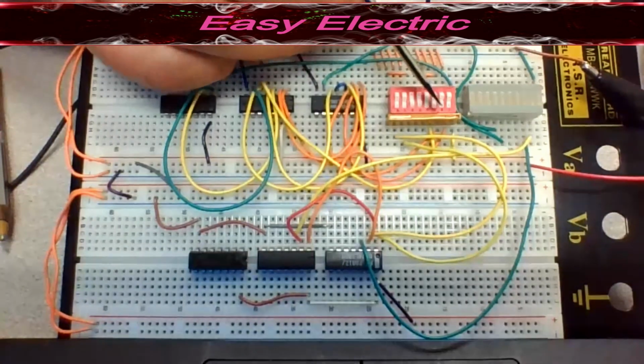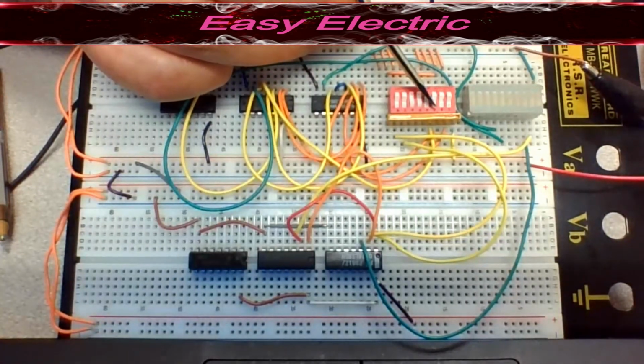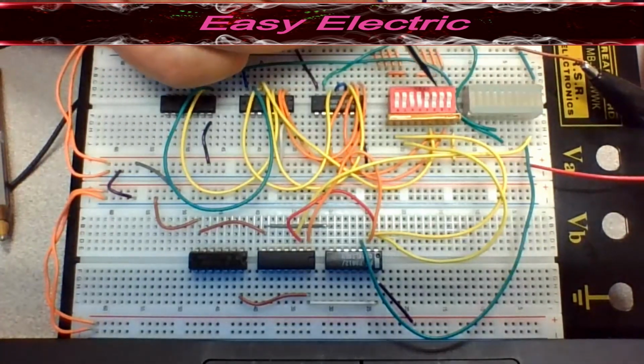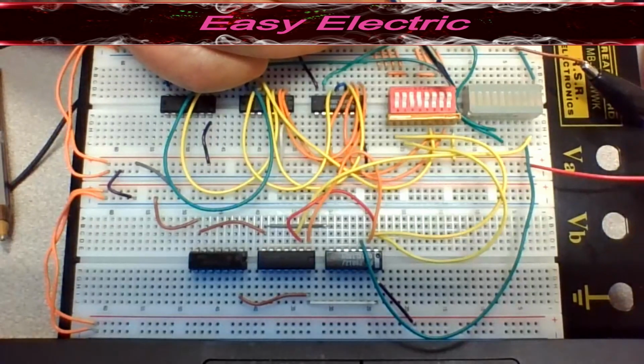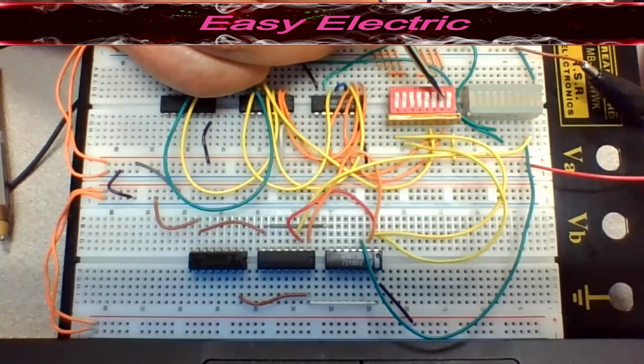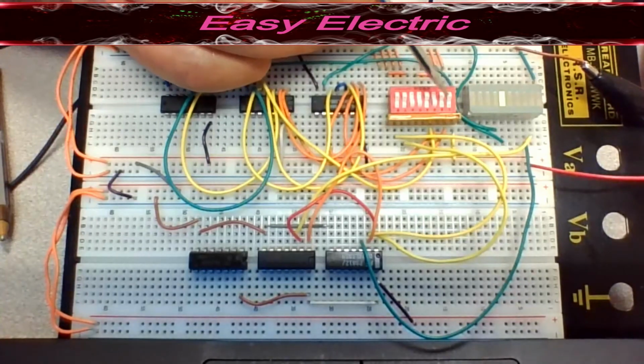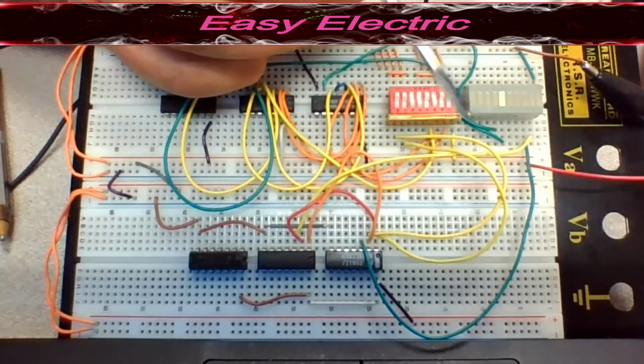So first, A, B, and C are all 0. That means you have 0 plus 0, so both outputs are 0, which you see here. Next, I give A 0, B 0, and just change C to 1. So that means I have 0, 0, 1, so the result should be 1. As you could see, the lowest value bit is on and the highest value bit is 0.